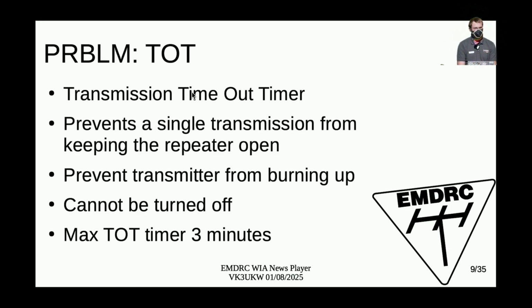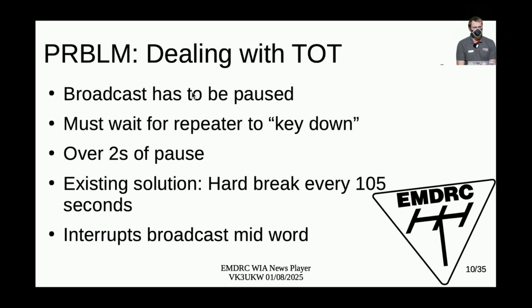Now, on that Yaesu digital repeater, that can't be turned off. The maximum timeout timer is 3 minutes. You can't get it any further than that. We had it configured to 2.5 minutes, and so we're going to have to work around that. Now, what you can't get around is that if you don't want to get locked out by the timeout timer, you have to pause the broadcast. So you can only broadcast 2.5 or 3 minutes at a time, and then you have to wait for the repeater to open up again.